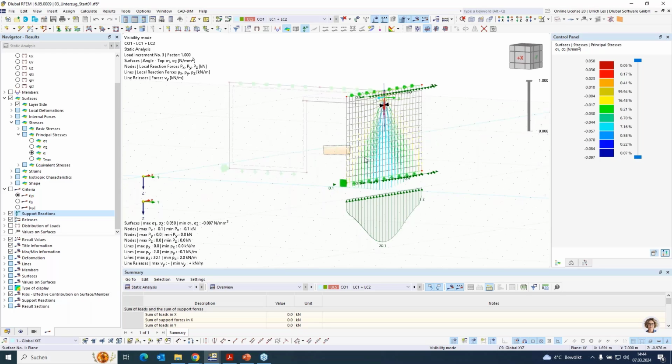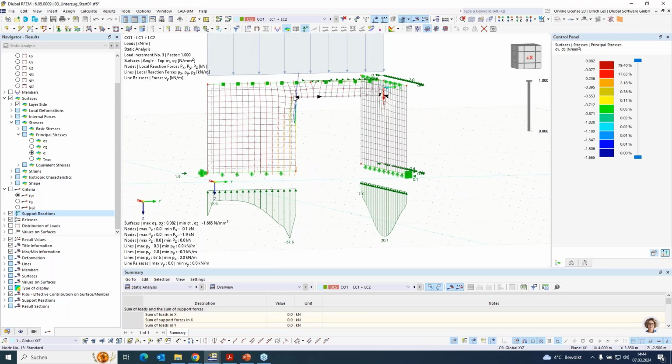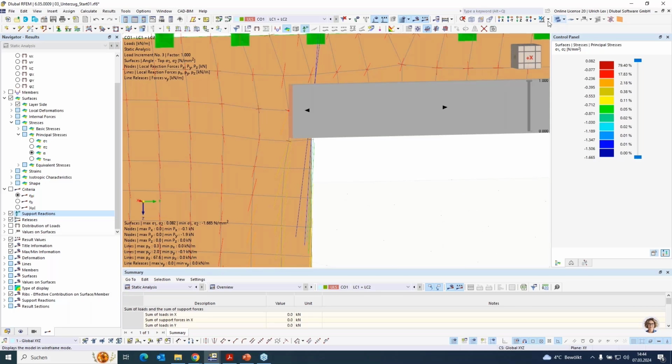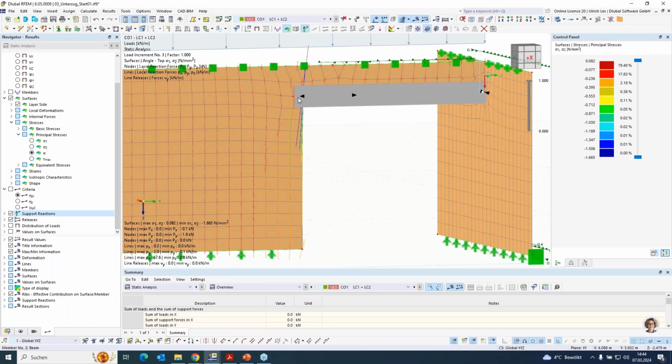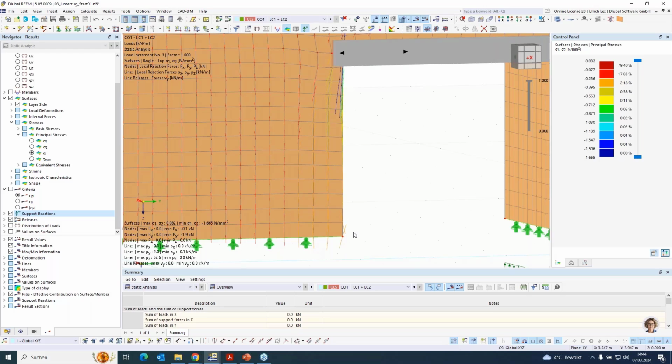Okay, on the second side, there could be problems too. When we have here now a too big force from the lintel, depending on what is on the floors above, it could be that on this place a concrete column should be located, but this is also easy to do.